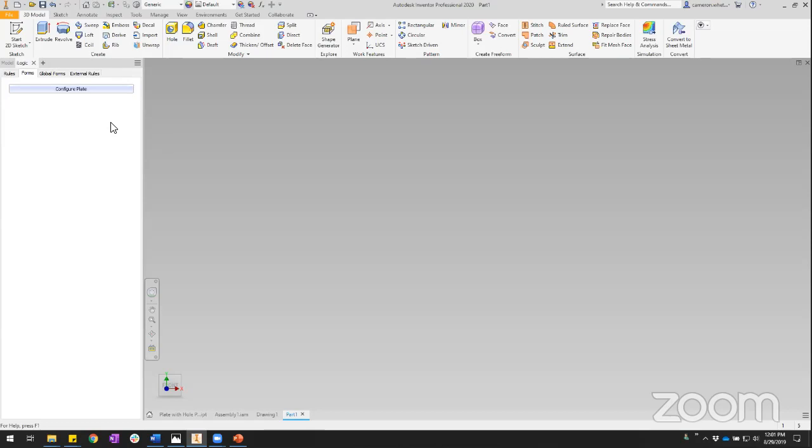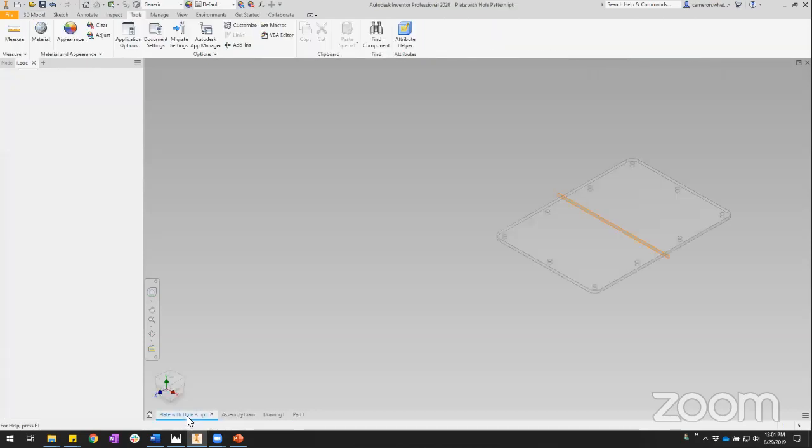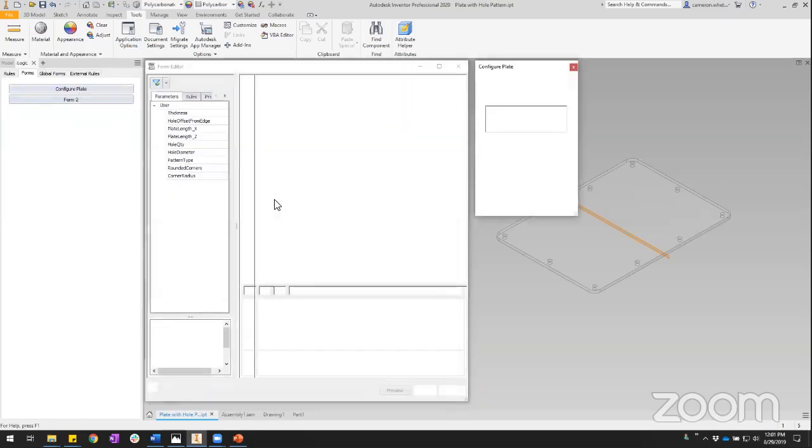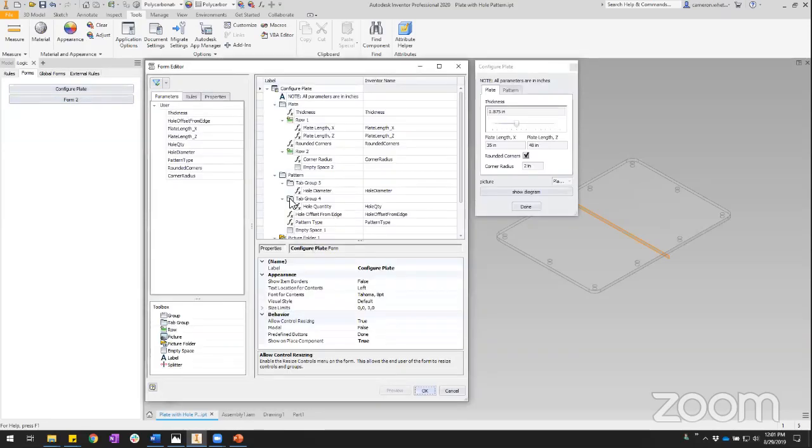Absolutely. And then for just one other thing too, for wrapping text on forms, Cameron, is there any strategy for that if the text is super long for some reason? Unfortunately, there's not a lot of options available to do that sort of thing. It comes down to what kind of trickery you can get away with by manipulating empty spaces, or like I said, if I wanted to wrap this, I could just put another note underneath it and then have the first note be half the text and the other note be the other half. Right, but nothing that restricts the size of the line and then immediately hits a return. It'll just keep going on forever.